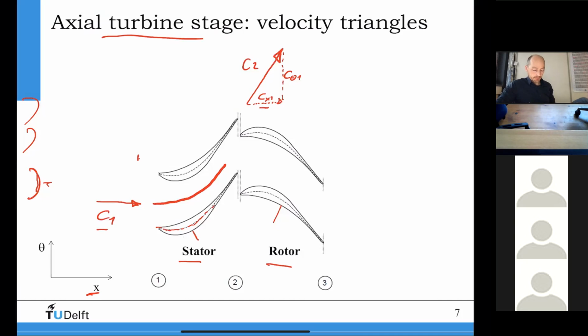but this is not the case in many turbomachineries, not for compressor turbomachineries. But anyway, now I do it like that. So now you can see that I have this part here. Now, how does the velocity triangle look like for the rotor? The rotor here will have a certain blade speed u. It moves in this case from down to up.